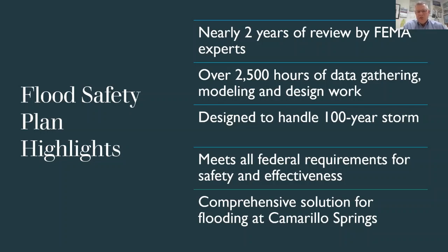In addition to design for the 100-year storm, it's not like the 101-year storm is going to cause it to overtop. FEMA is about statistics and insurance, and so there's a significant amount of redundancy and factor of safety put into all of the elements of a system like this.